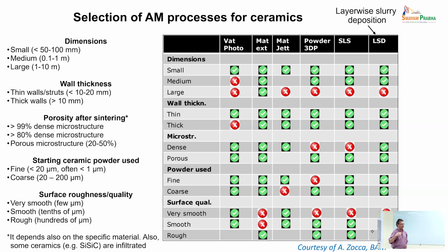The problem with depositing a layer of powders is the fact that you need flowable powders. I mentioned that this morning. And this leads to using coarse powders, hence a porous body after sintering.